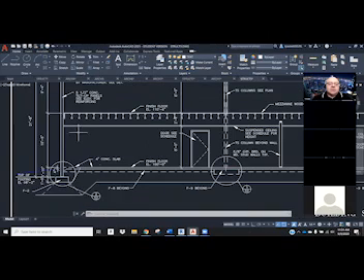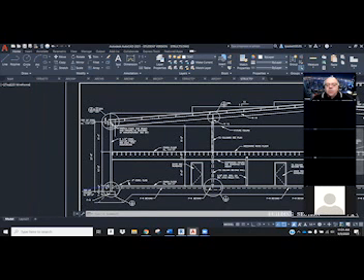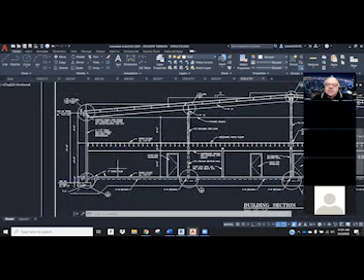So if I zoom up over to this portion, we find that this is a 5.5-inch thick concrete tilt-up panel. That means this is one solid concrete wall. It has rebar in it to keep it strong. And when they make these, they pour the floor first, then they oil the floor. They literally put down, usually it's almost like a vegetable oil. Then they will pour the wall on top of the floor. When that is set, they tip it up into place, and it's called a tilt-up concrete panel.